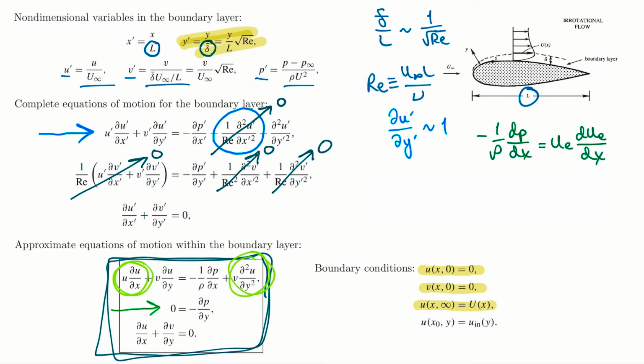Whereas the Navier-Stokes equations are what we call elliptic. And elliptic equations require specification on the bounding surface of the domain of the solution. So the Navier-Stokes equations are elliptic in velocity, and therefore they require boundary conditions on the velocity or a derivative normal to the boundary: upstream, downstream, and on the top and bottom boundaries. So all around the domain. And so the upstream influence of these downstream boundary conditions is of concern in the computations.